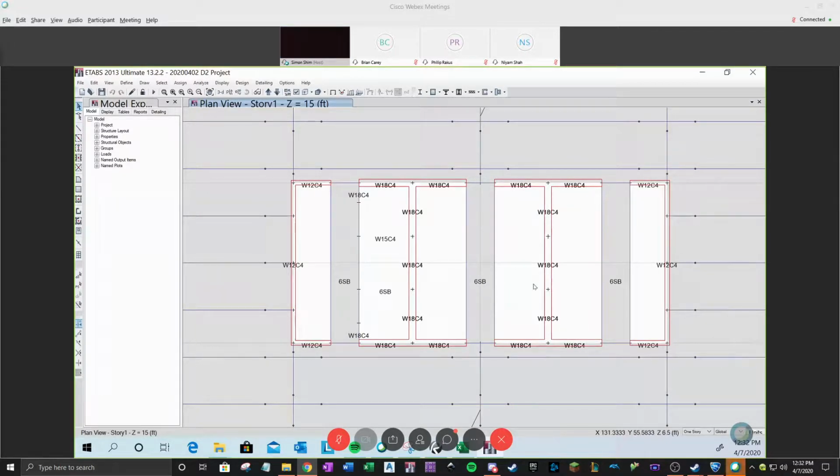To make the stiffness bigger, increasing flange thickness is the most efficient way. By the same analogy, since all the core walls are tied with link beams, this works more like a perforated box. So overall, the outermost wall thickness is actually more efficient than just increasing the inner wall thickness.